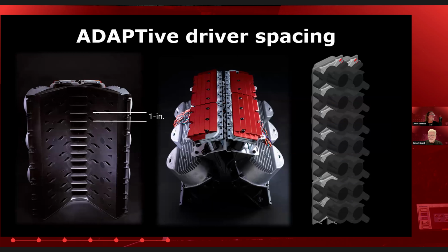So to reiterate what Robert was showing you earlier, I got a little deeper look into an adaptive mid-high engine for this. This one is Anya, and you can see here in the center the backside of all of the 1-inch compression drivers, which physically are actually larger than 1 inch. So how do we get them to be 1 inch spacing to make that technology work? If you look closely at this image, you can see that they're physically staggered next to each other, and their exits are 1 inch spaced diffraction slots.